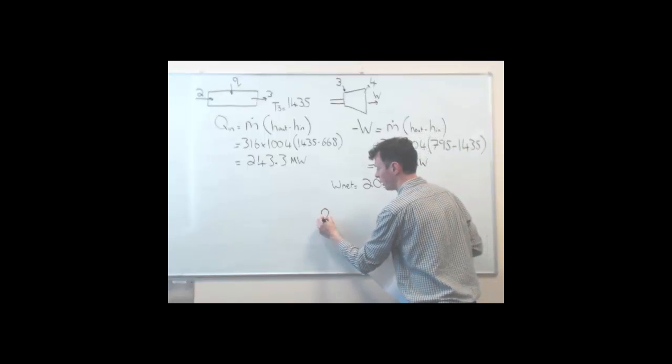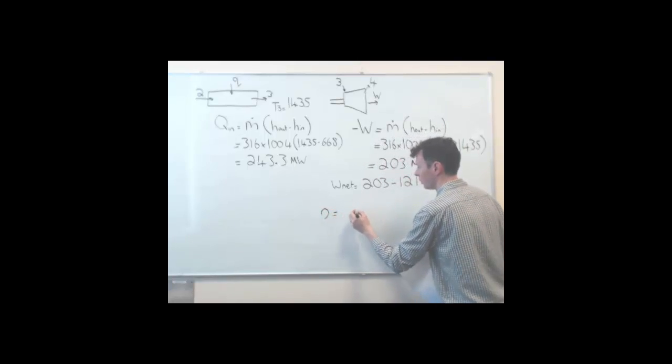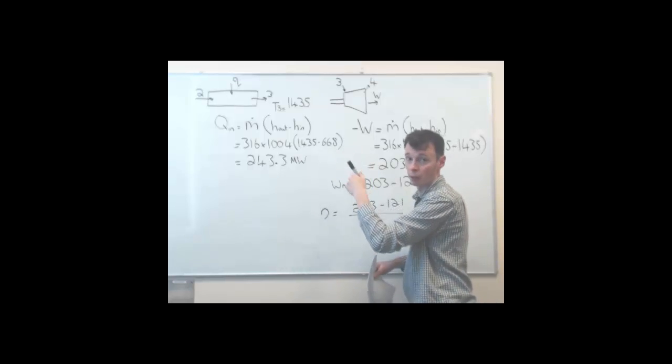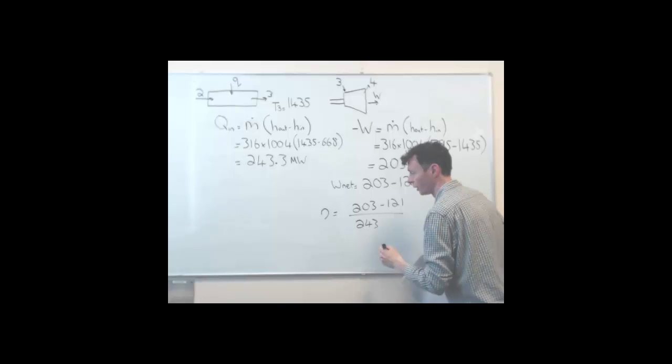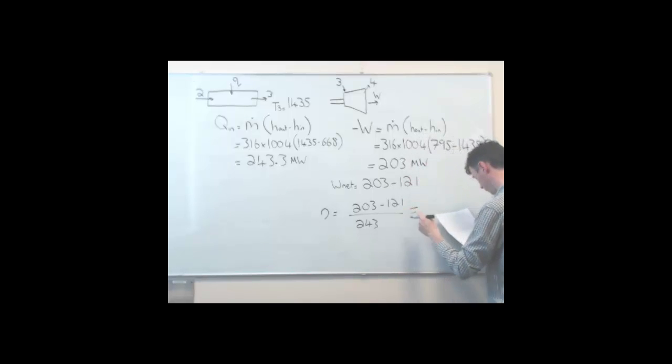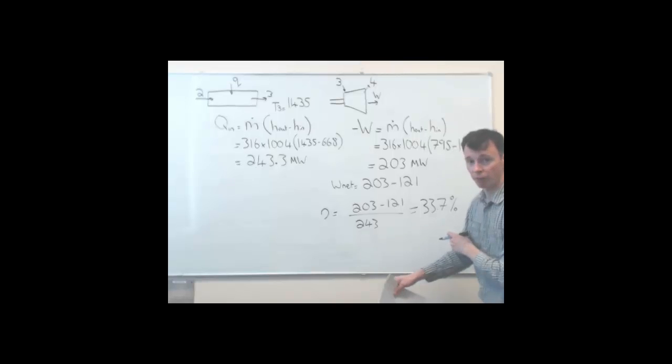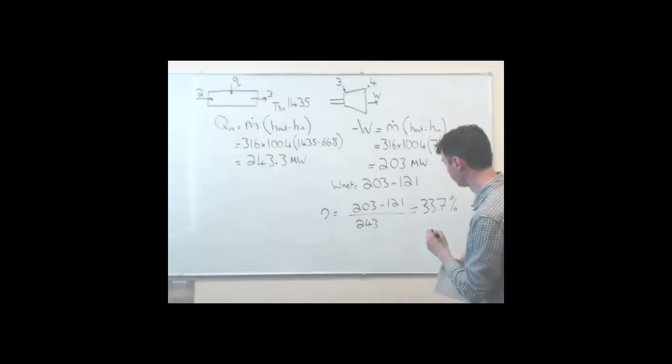And therefore the efficiency equals 203 minus 121 divided by the heat in, 243. And that gives us an overall efficiency of 33.7%, so 34%.